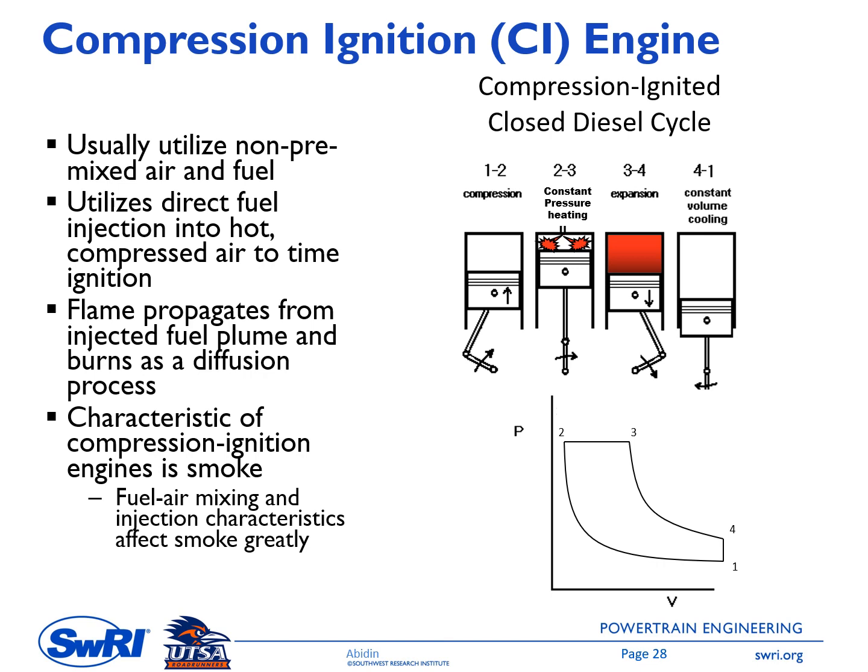So this is used to control emission. It can be a mixture of air and EGR introduced to the engine. We will learn this EGR role in chapter 11. And then at the end of the compression process, the diesel fuel is injected into the chamber. Because the mixture temperature and pressure inside the chamber is above the ignition temperature, the fuel will ignite by itself. Okay, and then the combustion process occurs.